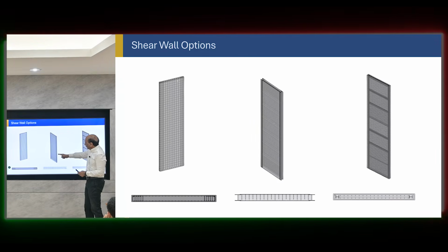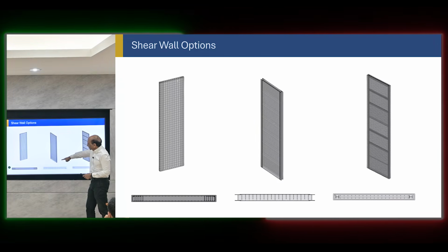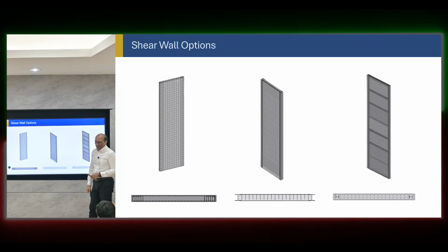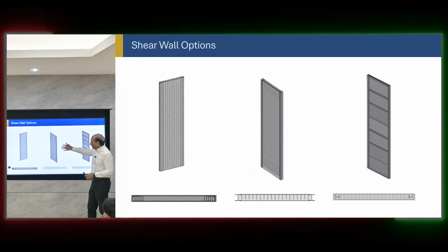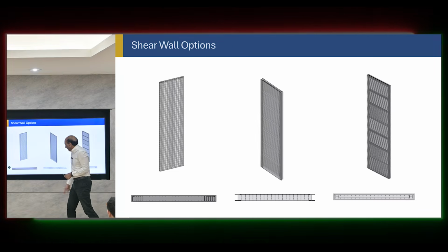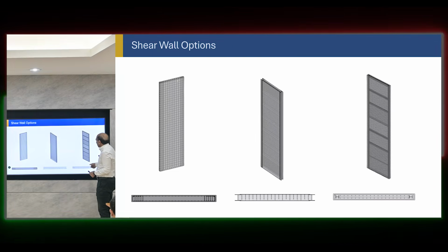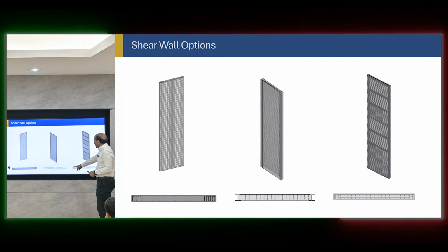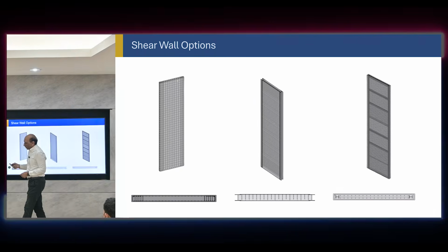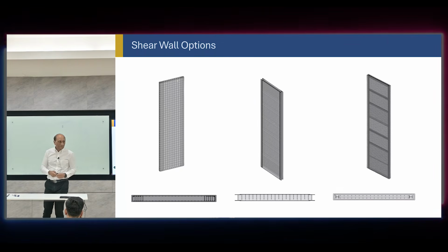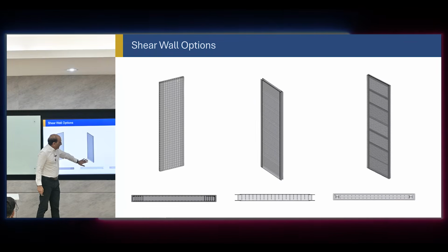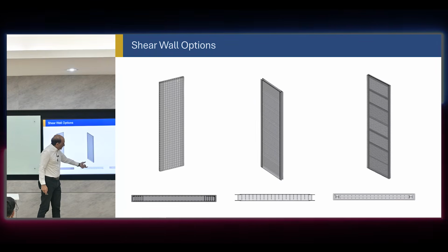And that's why this new system of the composite plate, steel plate with no reinforcement, has come up now. Very recent. People just thought, okay, why don't we just put steel plate on both sides and no reinforcement? This is the traditional one. This is the mixed or the composite core with the steel section inside, but still concrete outside. So these are the main three options that we will consider. Currently, this is expensive, but very fast in terms of construction, and the size is small.